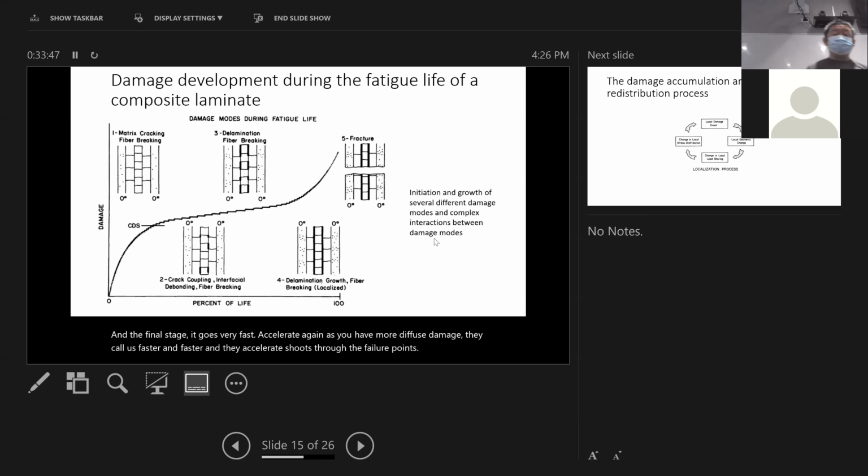So this is good and bad. The good is that you have a very stable middle period. You could have a very long fatigue life. Even though you have enough matrix cracks, things can last long. But there are no signs of final failure. The downside is that it's hard to predict and get warnings of when you should reject this part, when you should retire this airplane, retire this wing, change to new parts. No warning.